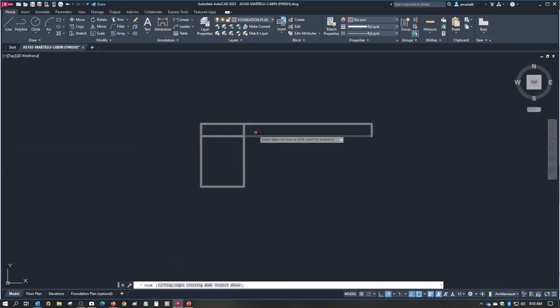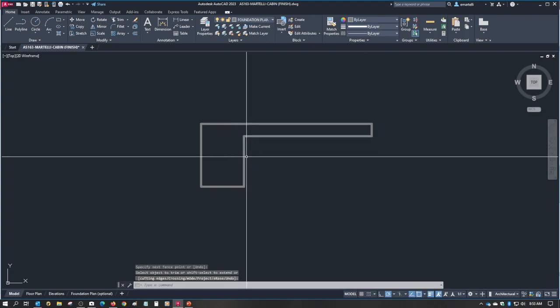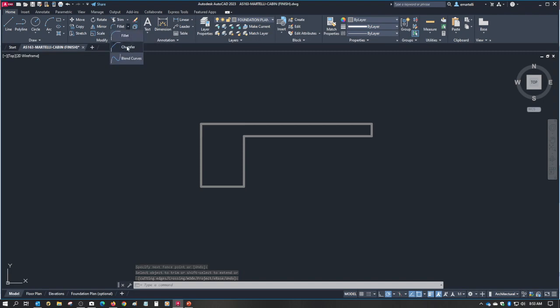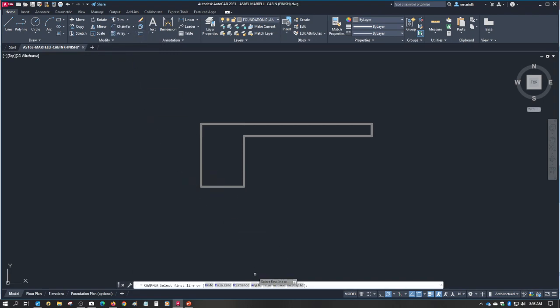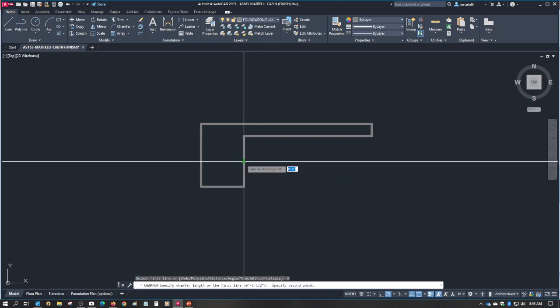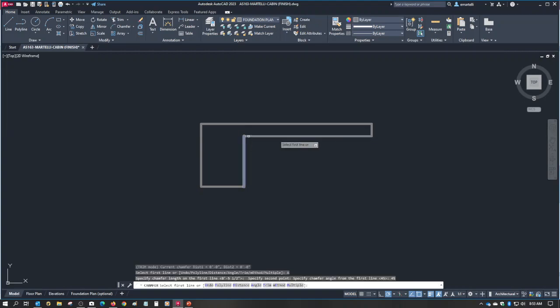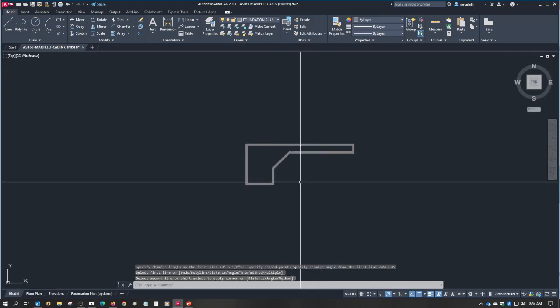And you can clean things up if you need to. But next, Fillet has a counter command called chamfer. The way chamfer works, if you look in the command bar, you can give it an angle. It's going to need the length. I'm going to pick the midpoint on the inside of the footer and then the endpoint up here. Then type in the angle of 45 and select adjacent edges. That's going to give me my footer.